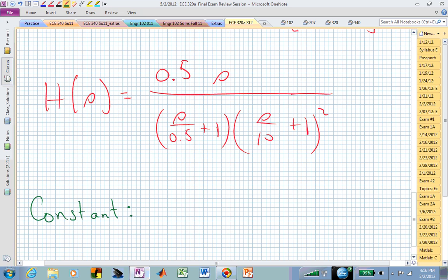We're coming up from the basement. So you should expect a sloping line coming up, and then we'll have 3 breaks after that based on the poles. This 0 at the origin will never break. It's just going to always give us this sloping line from the bottom lower left up to the upper right, and because it's by itself, it's just s. It's not s squared or s cubed. Its slope is plus 20 dB per decade. It will be shifted by this constant. The constant will shift the entire magnitude plot up or down depending on what it ends up being.